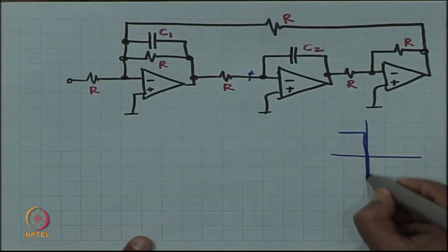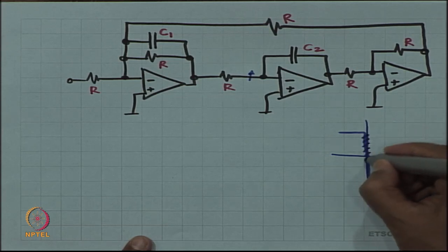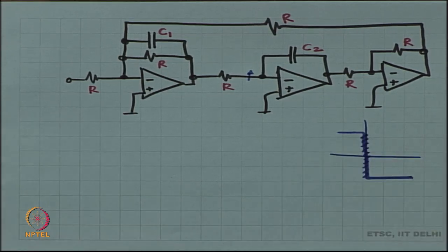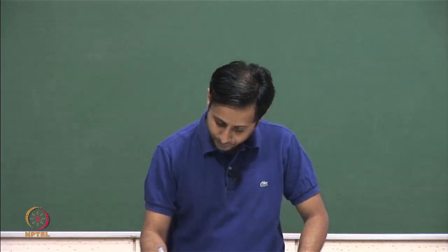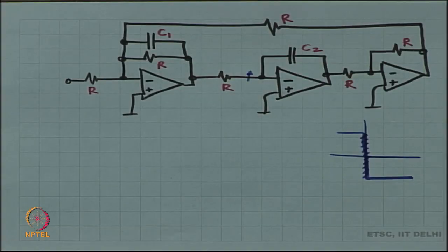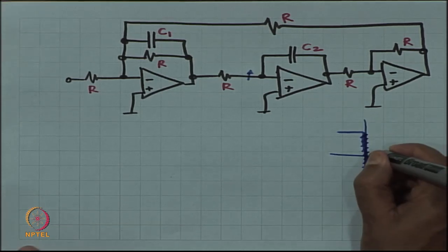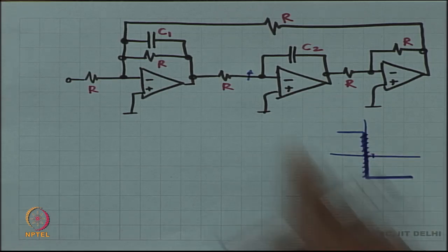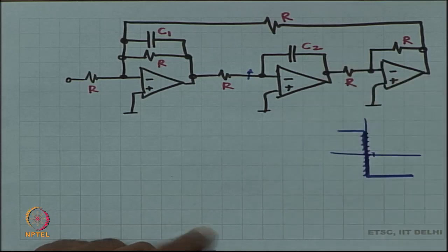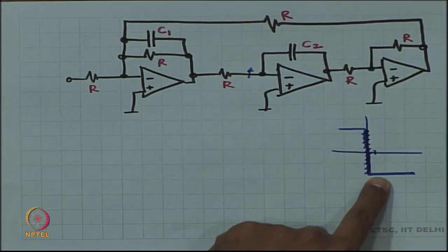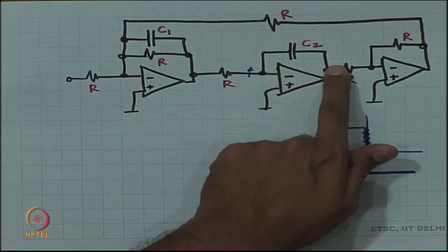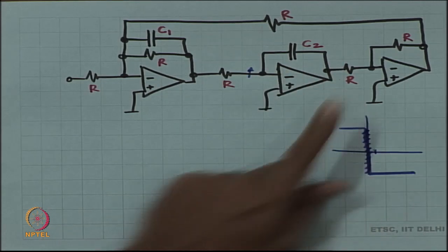Remember, in the previous discussion we discussed the op amp has to be in this high gain region, right. The other two regions are flat, there is no gain, the op amp has to be in the high gain region. So, the operating point of the op amp, that input voltage of the op amp has to be such that you are in this region. Okay. So, let us say you are not, you are slightly higher, you are somewhere over here. In which case, what does this mean? What is the output of the op amp? It is the lower power supply, right. You are slightly higher than required. So, therefore, this is very low.